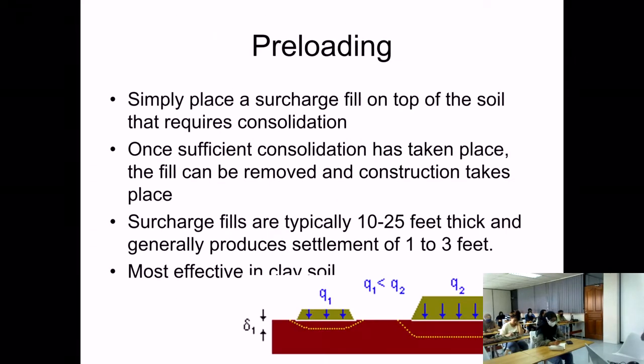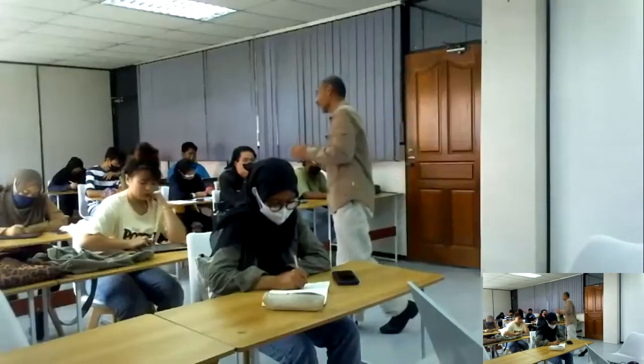Preloading, I mentioned just now how you give some exercise to the soil. We preload. So simply place a surcharge. Sometimes it's called surcharge. So if you come across the term surcharge in your contract document, that's preloading material. Sometimes preloading, surcharge, those are the terms in construction work.